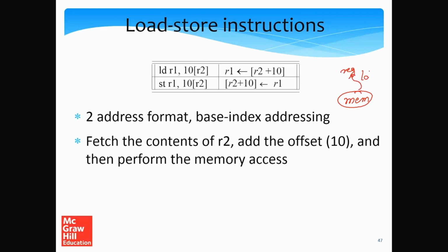And a store instruction's job is to take a value from a register and put it in memory, right? So a load instruction takes a piece of data from memory and puts it in a register. And similarly, a store instruction takes data from a register and puts it in memory.